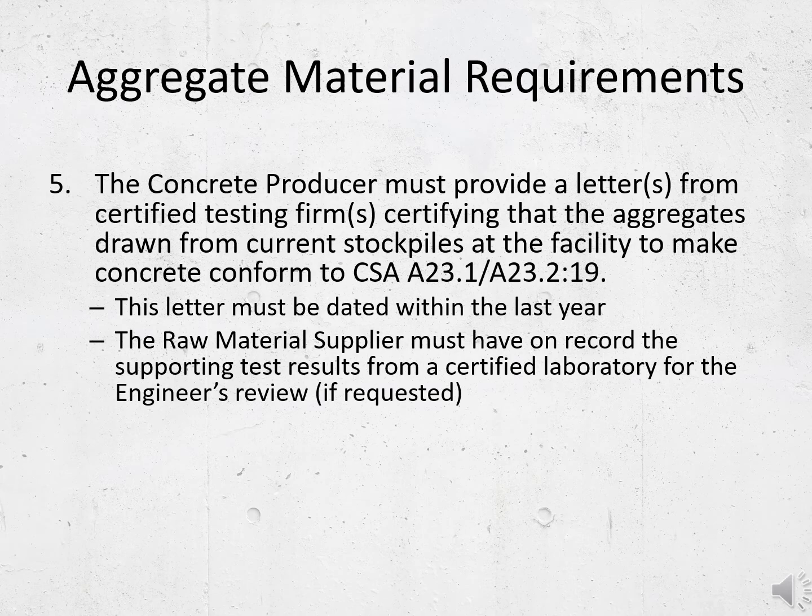In the case of aggregates stored in stockpiles or similar distinct and identifiable lots, test results older than 1 year may be accepted by the owner when the supplier provides affirmation that the results submitted pertain to the identified lot and are representative of current supply.